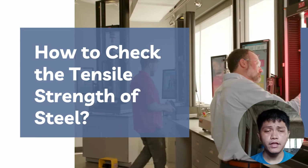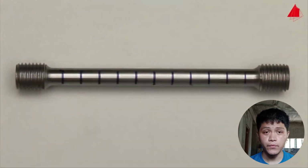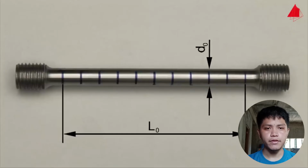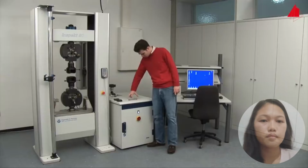Now, let us proceed to how to check the tensile strength of steel. First is to prepare the sample pieces. For example, this test piece has a cylindrical test region with an original diameter of 10 mm and an original gauge length of 100 mm. Within this test region, distance marks have been drawn at regular intervals. They help to visualize and measure the plastic behavior of the specimen.